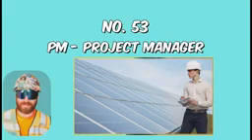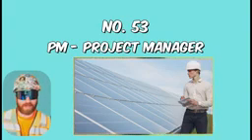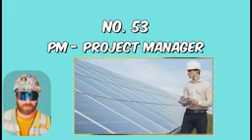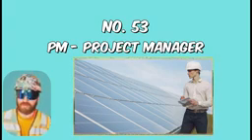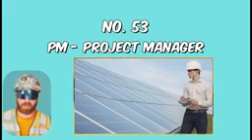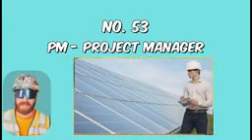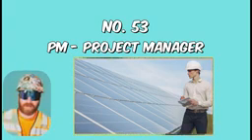Project manager, someone you never see on the job site but supposedly is involved with managing the project. Project manager's responsibilities are actually to manage risk through forward planning. They're the office counterpart of the superintendent who operates in the field. The project manager gets the material to the job site, and the superintendent gets the material installed on the project.